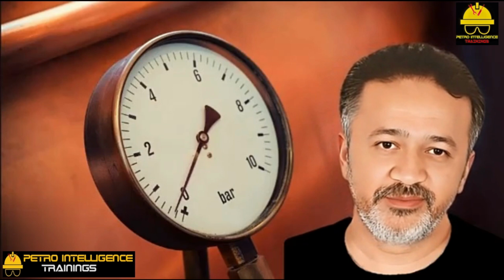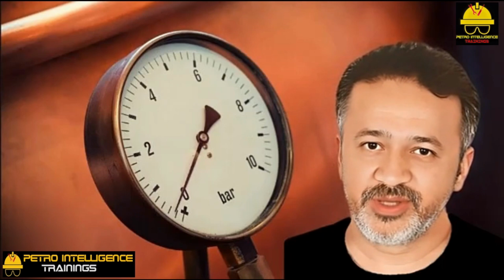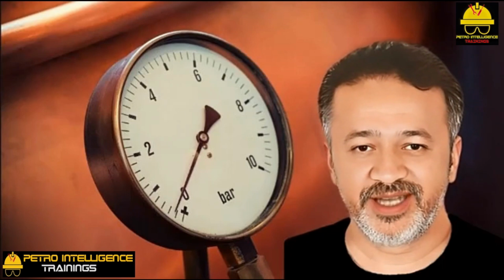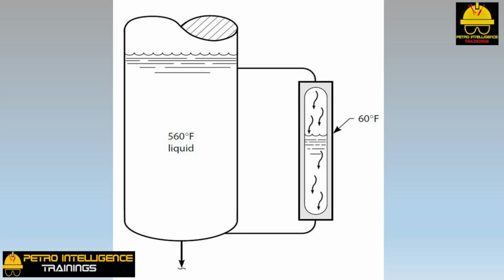High liquid level. In our calculation, we had 4 feet of liquid in the glass and 5 feet of liquid in the tower. But what happens if the distance between the two taps is 4 feet 6 inch? You can see a picture of the observed result. Liquid circulates through the glass, pouring through the top tap, and draining through the bottom tap. The apparent liquid level would then be somewhere between 4 feet 0 inch and 4 feet 6 inch, let's say 4 feet 2 inch. The indicated liquid level on the control room chart would then be 92%, that is, 4 feet 2 inch divided by 4 feet 6 inch.